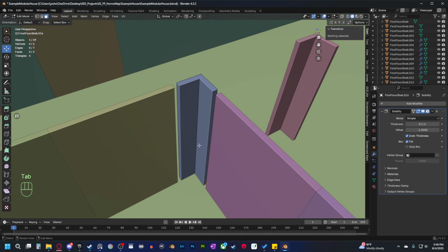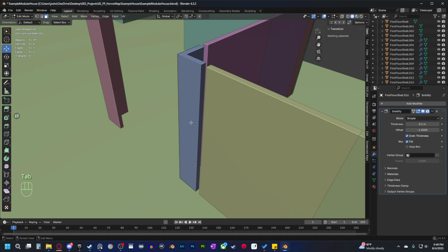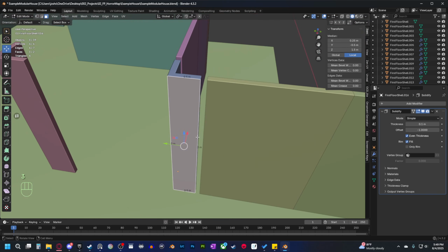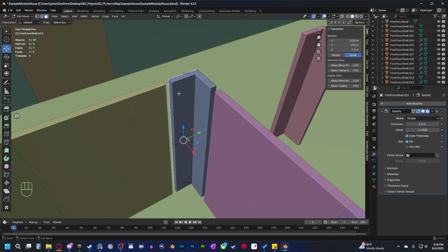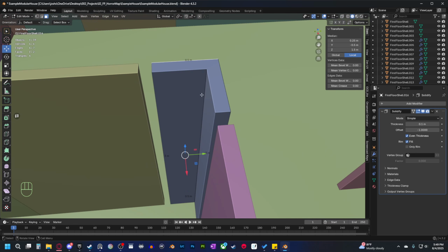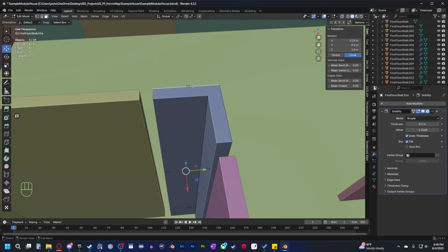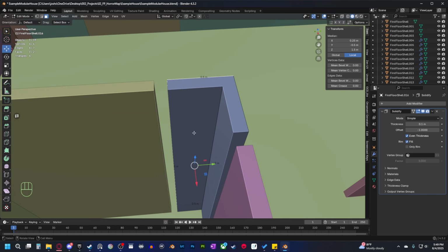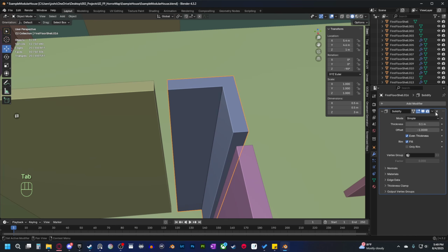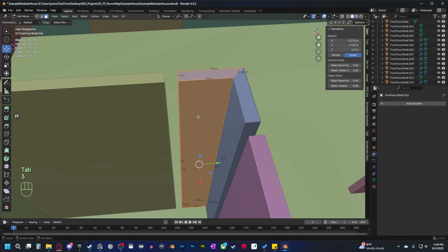And then it dawned on me that this piece, while it is 0.5 meters right here, which is what I need this distance to be, the thickness that we add to the wall, we added 10 centimeters of thickness, which means that when I apply this modifier, now you will see that the inner part right here is only 0.4.